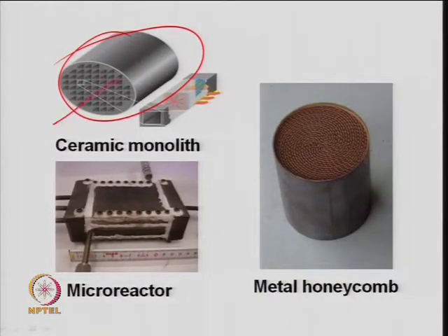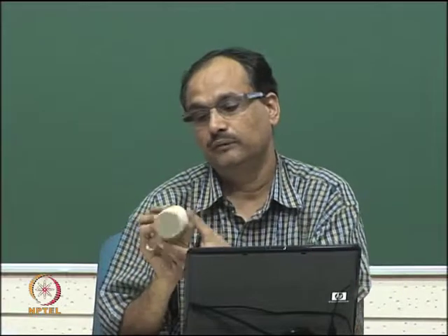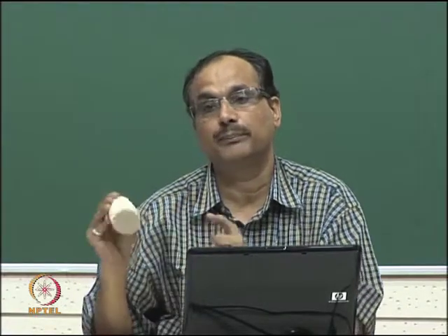Through this the reactant species pass, they diffuse also, axially and radially, and then they transfer into the reactor. So, large surface area per unit volume. For your automotive exhaust catalyst also this kind of structure is used. At the exhaust we put this kind of material, coated with platinum or noble metal, and then it handles all these NOx, SOx, COx. There are three-way type catalysts, reduction, oxidation, all these types of monolith catalysts are available, and these are now being considered for reforming.